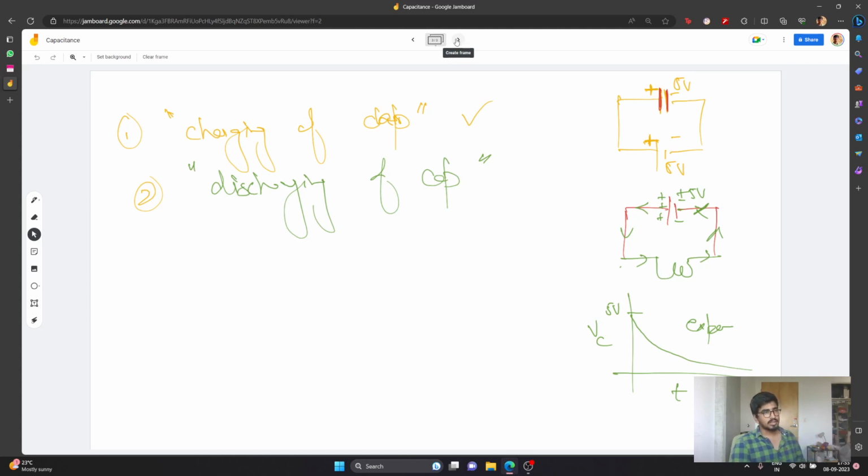and then the thing neutralizes, right? So all of that energy that was initially pushed from the battery to the capacitor was stored on the capacitor. You will see that if you transfer X amount of energy, only X by 2 gets stored on this capacitor, and this X by 2 energy that was stored is then dissipated through that sudden burst into the bulb, right?